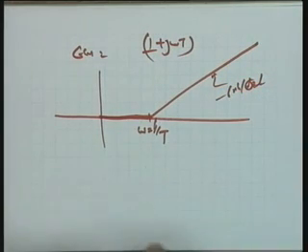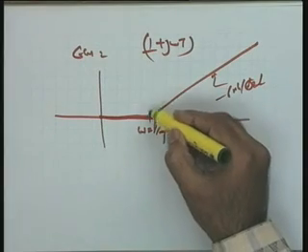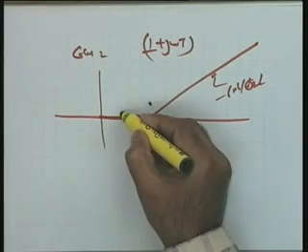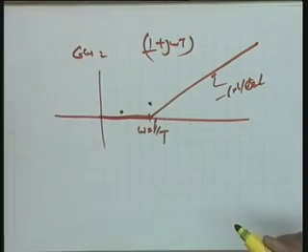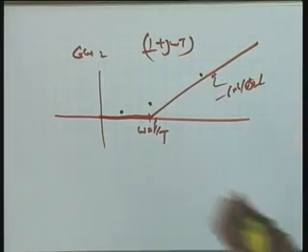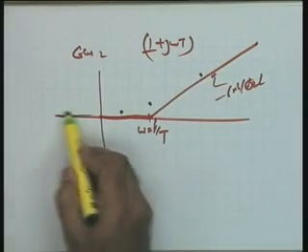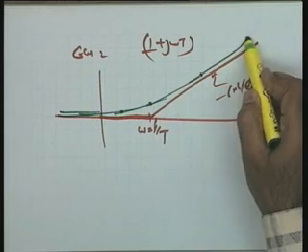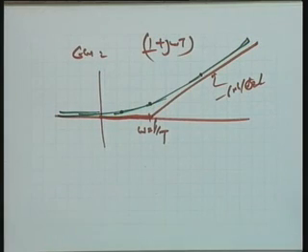Now you can check, the errors are going to be plus. You take 3 dB up, you take 1 dB up at 1 octave below the corner frequency, you take 1 dB up at 1 octave above the corner frequency, make a line asymptotic to the two, and you get this particular thing. Okay, I hope you are getting my point.